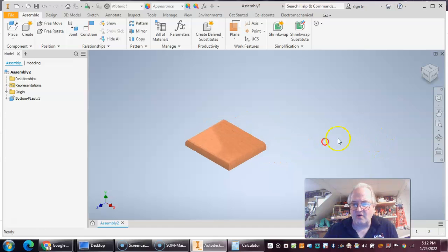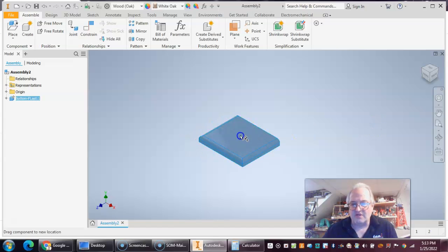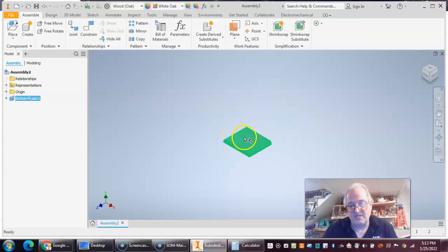Now notice my mouse is over here and I'm moving it, but notice when I grab the piece here now, I cannot move that. So I have locked that in. I have eliminated all what we refer to as degrees of freedom, and I'm going to talk more about degrees of freedom here shortly. So because we've got to lock in these degrees of freedom and prevent movement on it. Now, all of the other parts that we want them to kind of move, but we're going to fix those to this piece so that they don't move from there.